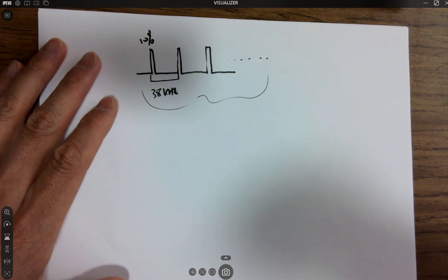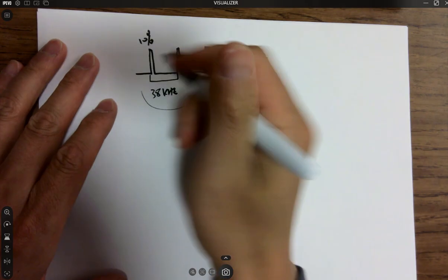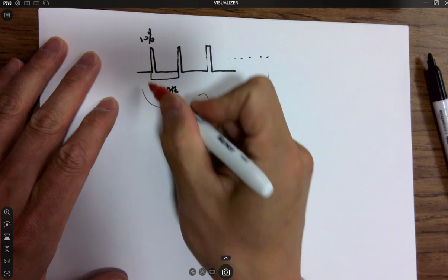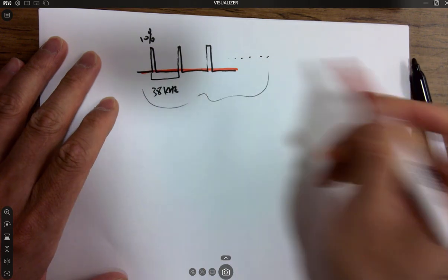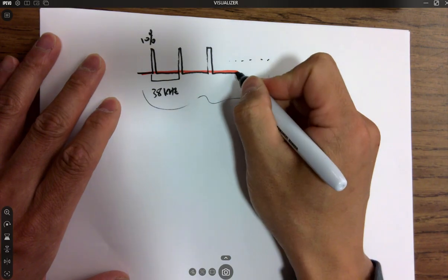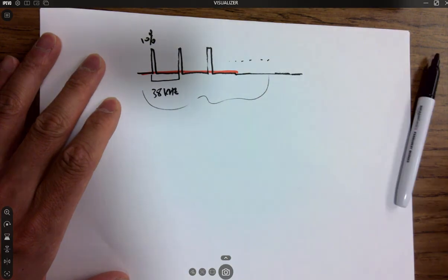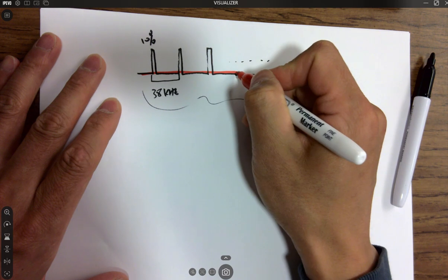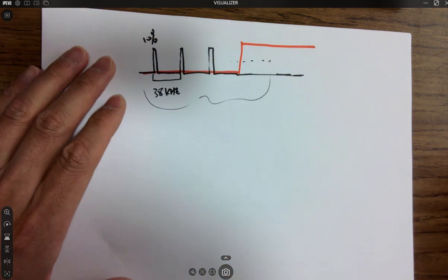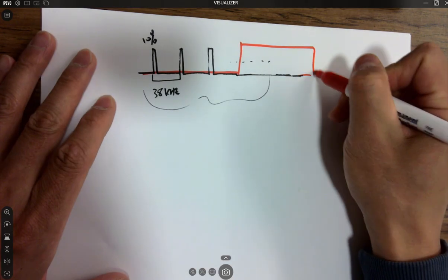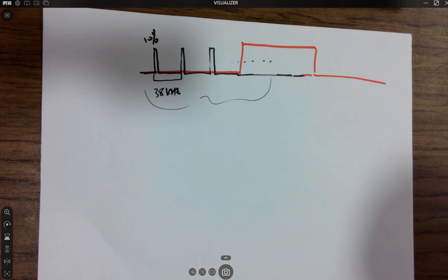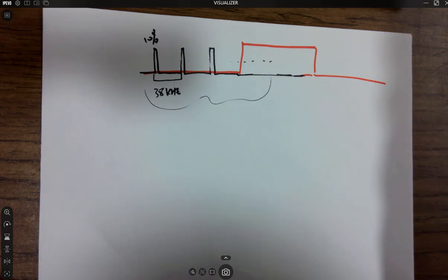and it's being sent to the air, and the decoder is going to receive it. Whenever there are pulses, it responds with 0. And if there are no pulses, like just 0, the decoder will respond with 1. That's how that works. And the decoder has an output, right? Think about that. The pulses are being sent into the air, and the decoder receives it.